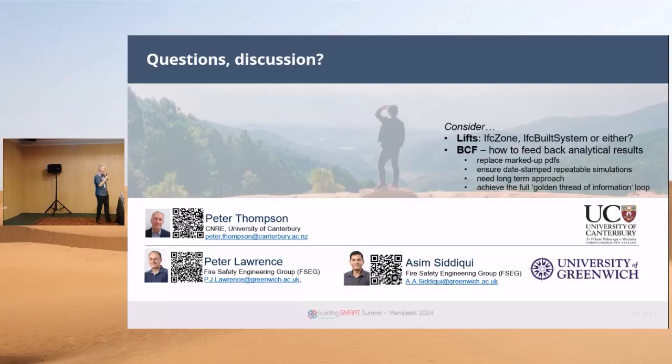And then we group these segments with IFC group, so we can have different segments in several escape routes, because they come together at specific places and then they merge like this. And we didn't want to duplicate elements, so we grouped these elements with IFC group.